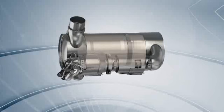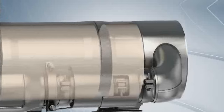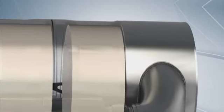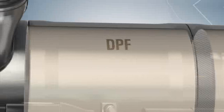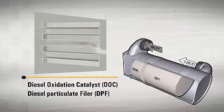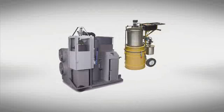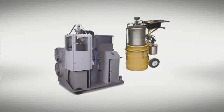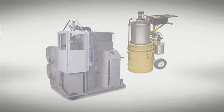Machines using the CAT C7.1 ASSERT to C18 ASSERT engines have a serviceable canister containing 2 aftertreatment devices, a diesel oxidation catalyst, or DOC, and a diesel particulate filter, or DPF. As exhaust streams through the canister, the diesel particulate filter fills with soot deposits and needs periodic regeneration to remove the soot and maintain filtering efficiency. Ash that accumulates in the filter is removed every 5,000 hours using a special service procedure that requires the filter to be removed from the canister.